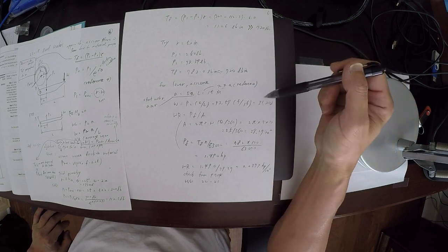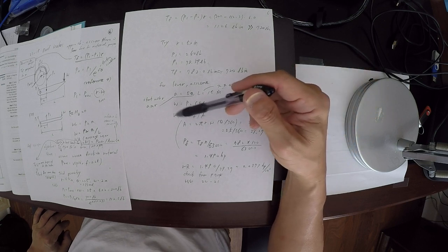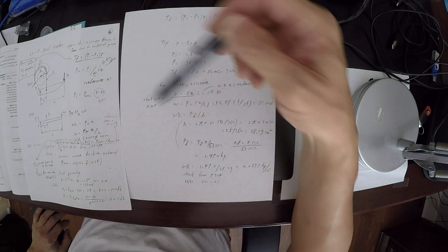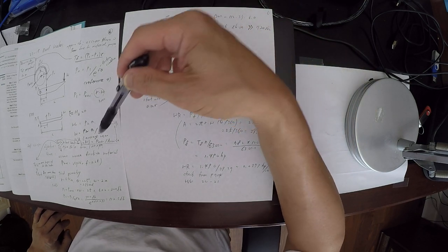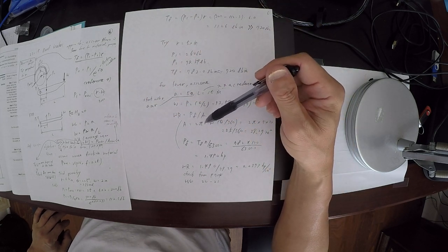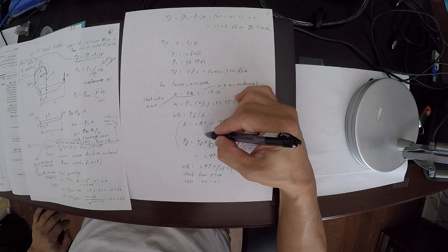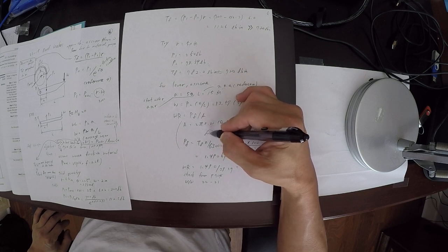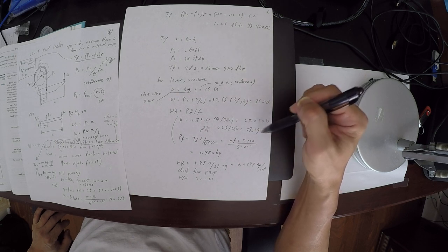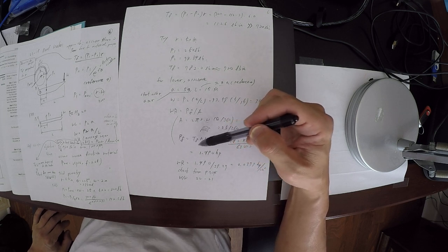Once you have this W, this is basically the force you need to apply. And then WR is something you also need to consider, which is the average wear ratio. Again, it is power divided by area, and the area is simply the circumference, 2 pi r, times width. That gives you the area, which gives us the value of 39.27 inch square.